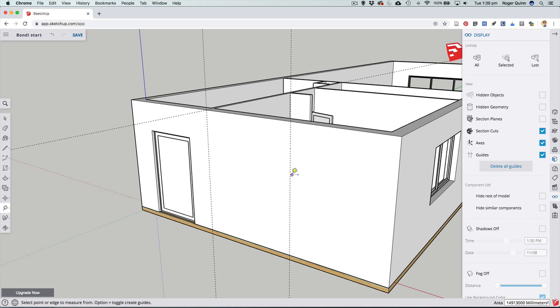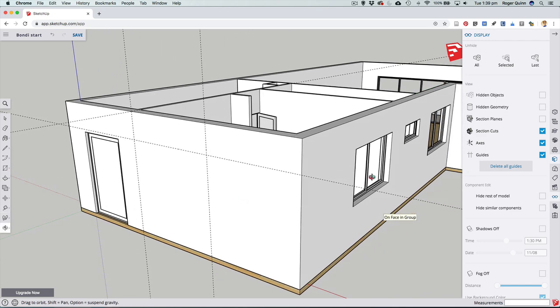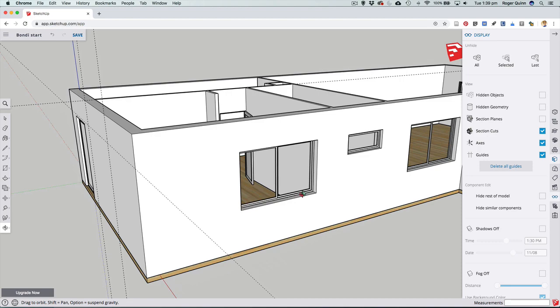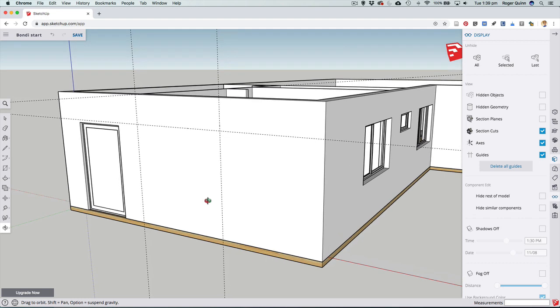The windows I want to make, all my windows on this particular model, are 2100 high, so I'm going to drag a guide, drop it anywhere up there, type in 2100, and there's my height for my windows. And to be consistent with this window over here, this window was 1800 wide by 1200 high. So I'm going to put in some guides to represent that. I'm going to go off the center line. I want it 1800 wide, so that means half of 1800, which is 900.